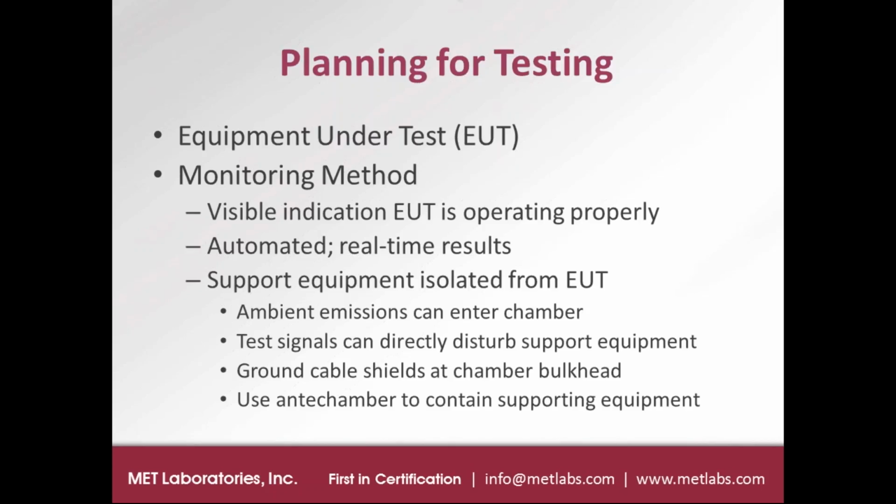You also need to consider a monitoring method and be prepared to provide that monitoring method to the test engineers. The monitoring method should provide a visible indication that the EUT is operating properly. That could be a laptop computer or support equipment with a test script that displays pass results when it's working properly.